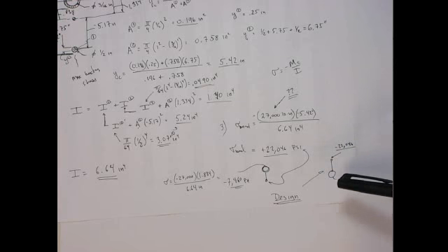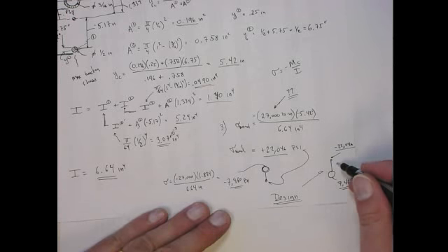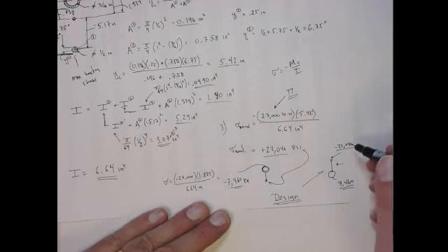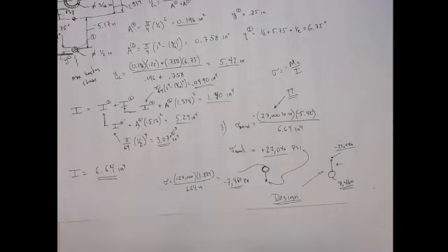so that you can use these things to help actually design, right? So, this is obviously steel, but if you had a concrete structure, where it can support much higher loads in compression than in tension, you would actually prefer a geometry like this, okay? Still have the same maximum stress, absolute value, but we've designed this such that it's in compression, as opposed to tension, all right? Okay, thanks. Sorry for the confusion on the C's, but that's an important point.